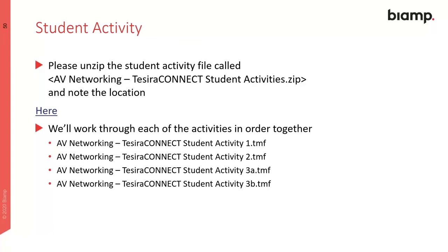Can a port on a TC5D have combined roles, for example Dante and control, to another normal switch like a Cisco SG350? So I think the question is whether you can have both Dante traffic and control traffic on the same port. Yes, that is possible. For example, I think the Shure mics do Dante and control on the same physical interface. So that's something that we certainly support. So any normal traffic with both AVB and Dante is okay.